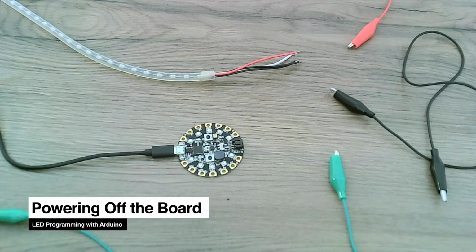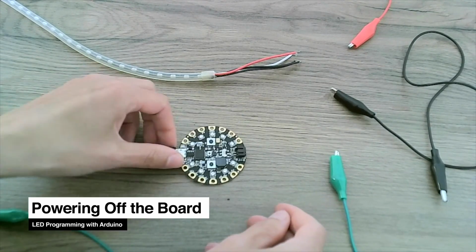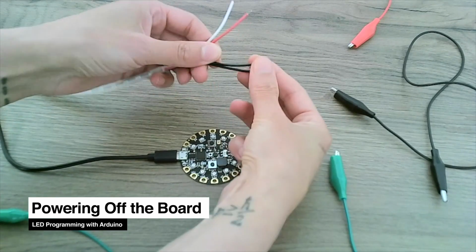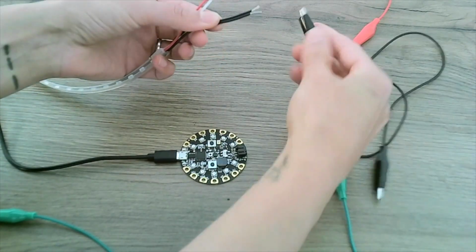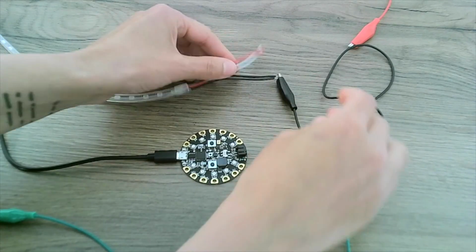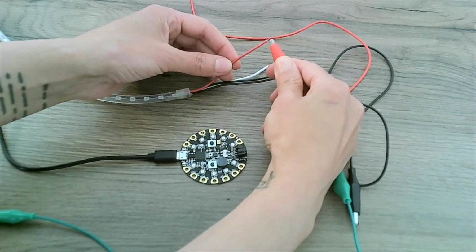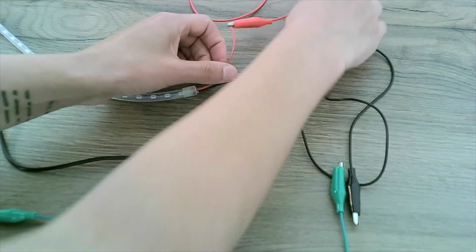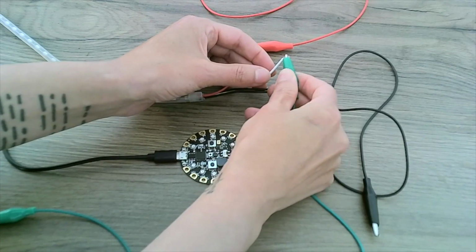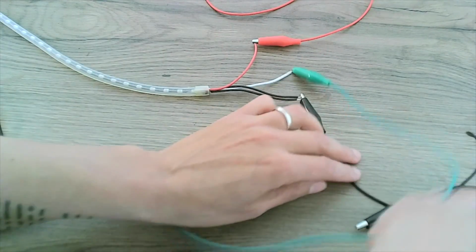It is acceptable to power a small amount of LEDs off of the Circuit Playground itself. To do so, you need your LED strip and you need 3 alligator clips. You'll want to attach both of the grounds, if there's 2, there might just be 1, to the black alligator clip, and then attach power to the red alligator clip. Finally, attach your data line, which could be white, green, blue, yellow, or another color, to the green alligator clip.